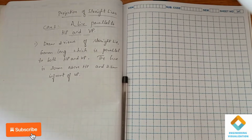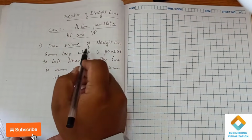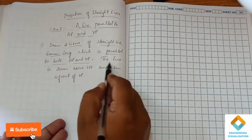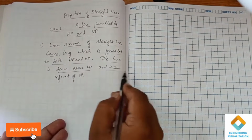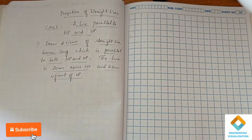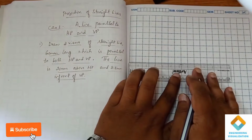You can see that two views you have to draw, front and top view, of a straight line 60 mm which is parallel to both HP and VP. The line is 20 mm above HP and 25 mm in front of VP. So here we are going to use only the first quadrant. First I am going to draw an XY line here.